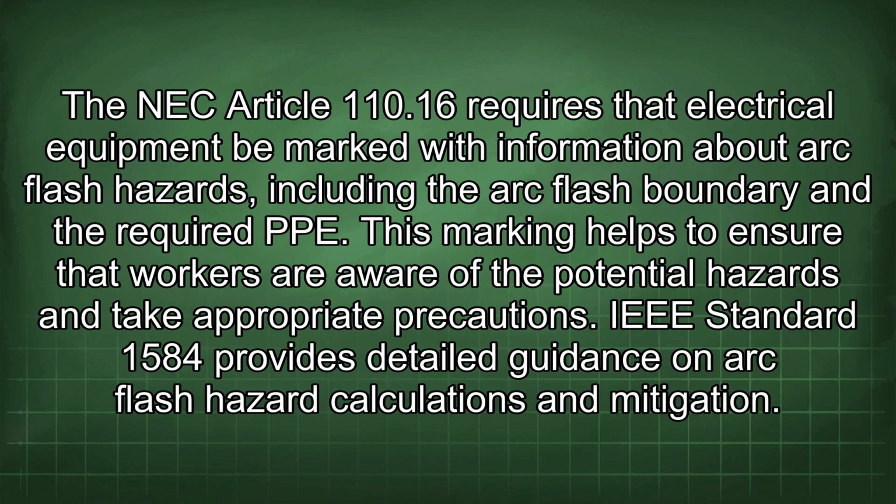NEC Article 110.16 requires that electrical equipment be marked with information about arc flash hazards, including the arc flash boundary and the required PPE. This marking helps to ensure that workers are aware of the potential hazards and take appropriate precautions.